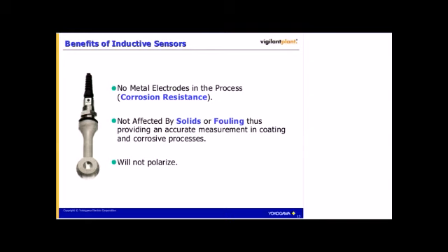Also, attention needs to be given to the material of construction. Inductive sensors are available in a wide variety, such as PEEK and Teflon. PEEK for the most common measurements, and usually Teflon for high concentrations of chemicals such as sulfuric acid.